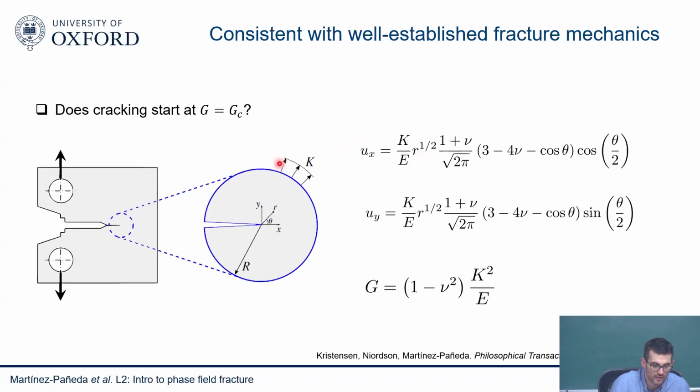So then if I apply this K field, what I want to see basically is, okay, now let's simulate the same problem with phase field. People do this all the time, right? They apply a K field and they look at the stress fields and so on. Now we're going to solve the problem with phase field, and we're going to see, okay, will crack growth occur when K equals the toughness, or in other words, when J equals the critical energy release rate? We'll do that.